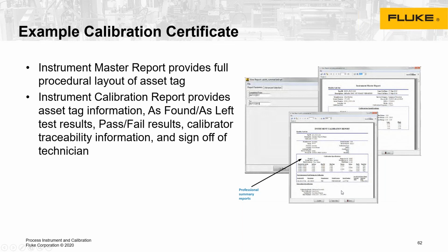And then below that, similarly, when the calibration procedures are passed back and forth, the calibrator passes its manufacturer, model, and serial number along with the data. So we said at first it was very important that when we put in the Fluke 754 with the serial number, we make sure we have the serial number of the calibrator in. It matches those three things, and then the certification is able to say that the standard used to calibrate this asset was a Fluke 754 with that serial number.